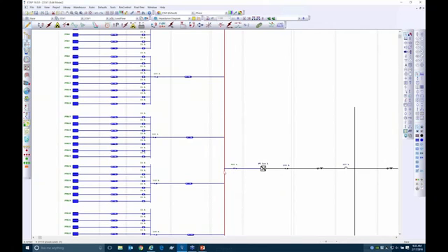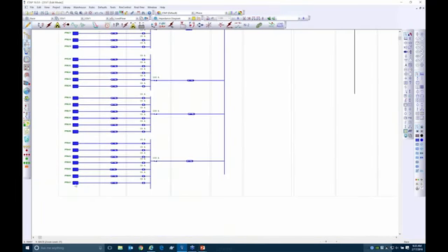So actually, technically, this DC bus is part of the inverter, and this bus right here is the combiner. And these are the individual fuses that we retrofit later on inside the combiner box to create a fused disconnect. So you'll see about 47 of those here.